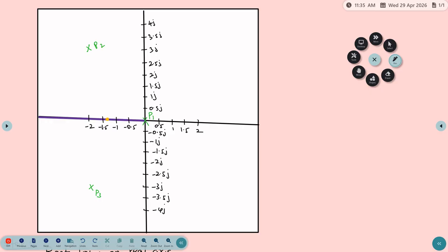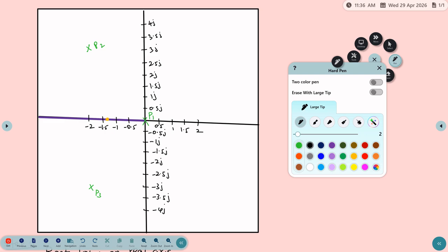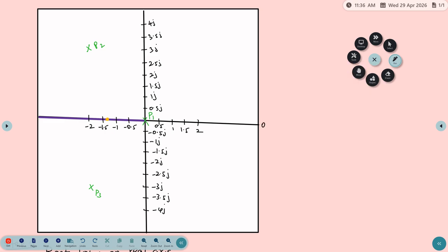a reference line for 0 and 180 degree. Right, already we are having reference line for 0 degree and plus or minus 180 degree reference line. So this same line is for angle of asymptotes also. There is no necessity to redraw that 180 degree reference line. We should mark that plus or minus 60.